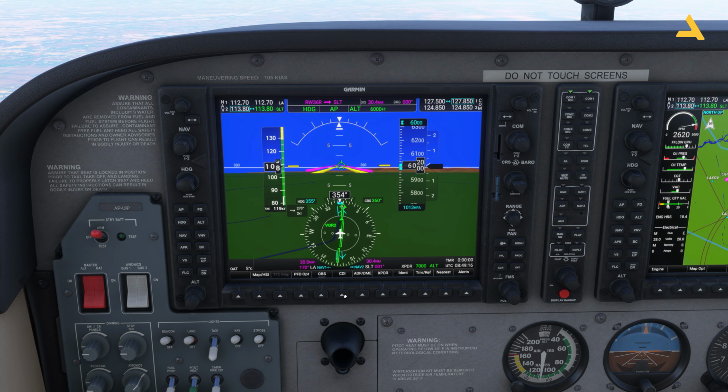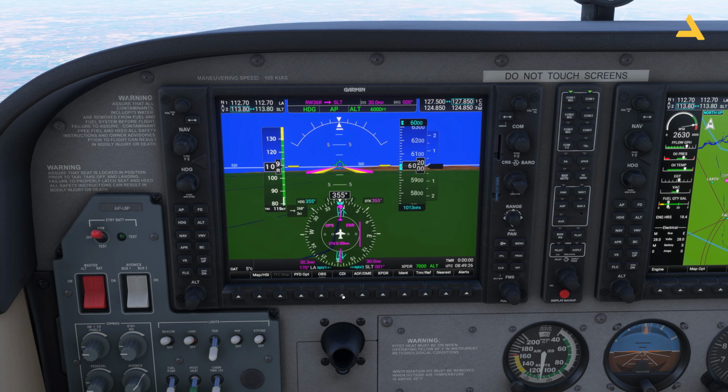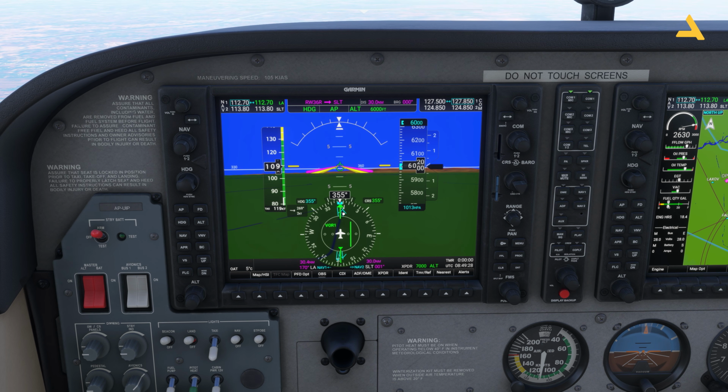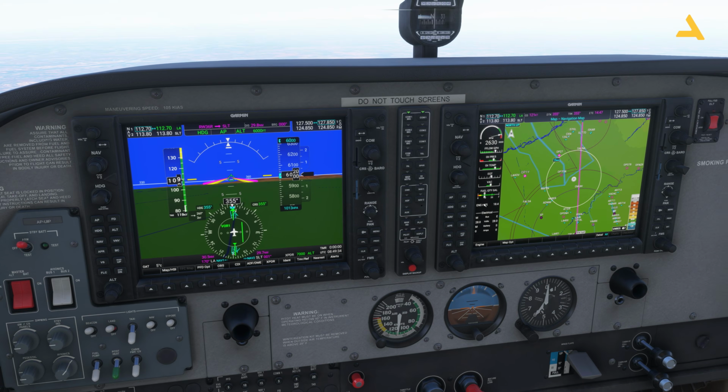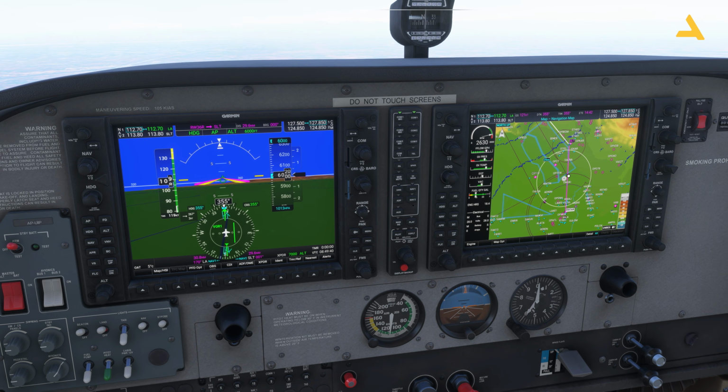And if I change the CDI, you can see I can also track the other VOR for the Sialkot. And let's get rid of it. And you can see there's deflection. Okay. Now I'm flying parallel to this line, which is not right, because if I keep on flying parallel to this line, I will end up somewhere here, not on the SLT. So I have to follow this.